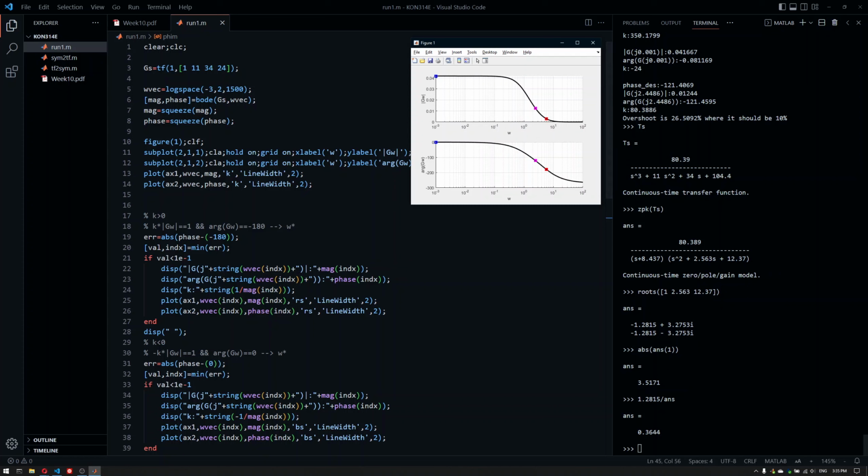At this point, it seems like you know that this is an LTI system. You know the order of the system. Why not use the time domain representation? So if you know the model well, if you're sure that your transfer function represents your system very well, you should opt for the time domain methods.